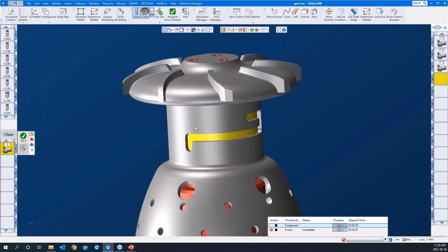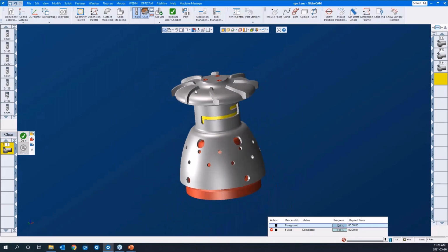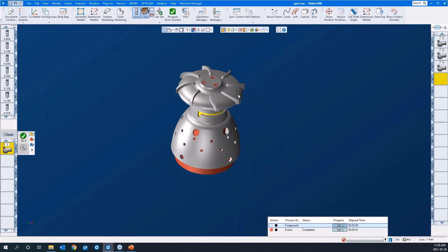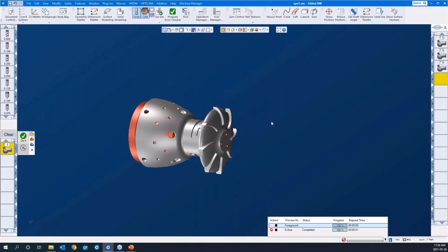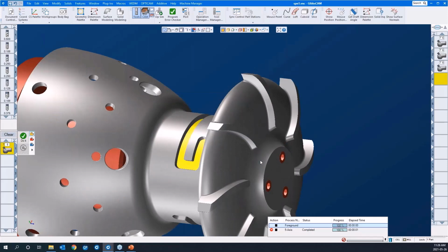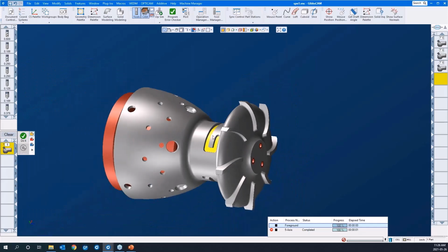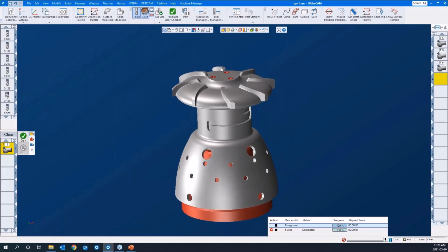Okay, we're going to look at this radial slot here. This is a 5-axis machine. It has full 5-axis on it. However, if we were to rotate the part along the trunnion axis 90 degrees and access this slot, in a sense, we're now on a 4-axis mill. Although this is 5-axis, this certainly can be done on your 5-axis or your 4-axis vertical mill or horizontal for that matter.